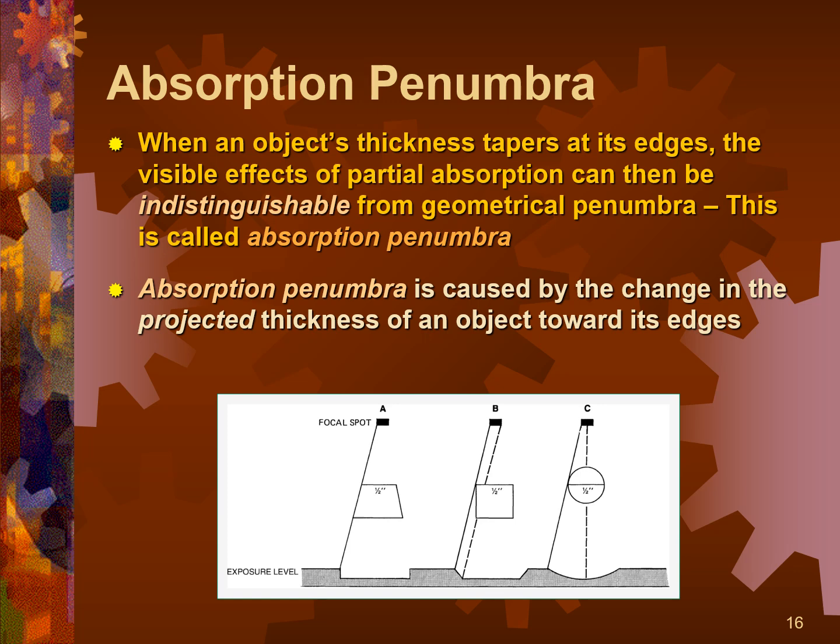Okay, with a spherical shape, the absorption penumbra and the tapering of the object from its true diameter, the X-rays are going through less and less of the object in a linear distance, and so there's less attenuation in any point of the sphere except for the center. The center is the point of maximum diameter, therefore maximum attenuation. Okay?